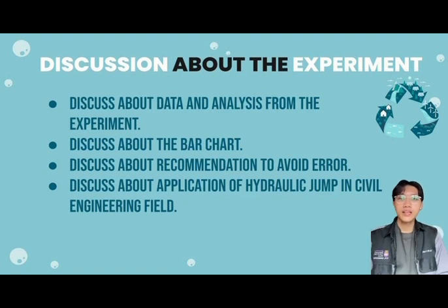In addition, it illustrates that upstream depth increases as the downstream depth also increases at the constant discharge and different height of sluice gate, whereas an increment in the downstream depth is obtained as the discharge increases at constant upstream depth. Froude number at the upstream depth boosts as upstream depth declines, which can be attributed to the increase in flow velocity. On the other hand, an increment in the upstream Froude number is achieved by increasing the flow discharge at upstream depth. Moreover, a significant increase in Froude number is recognized as a result of minor increment in the upstream depth compared to the change in flow discharge.